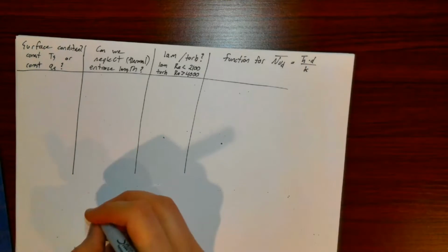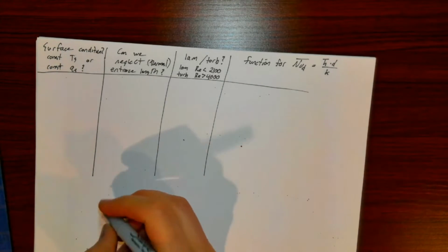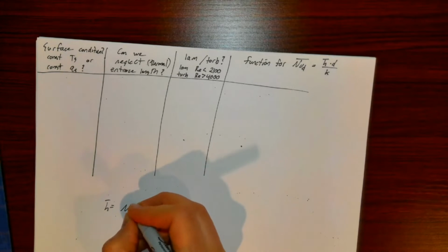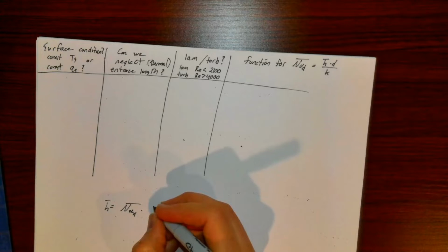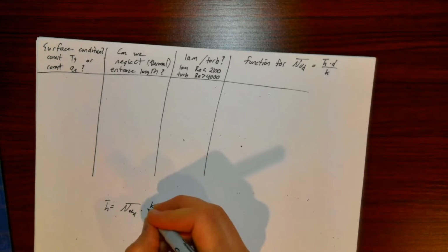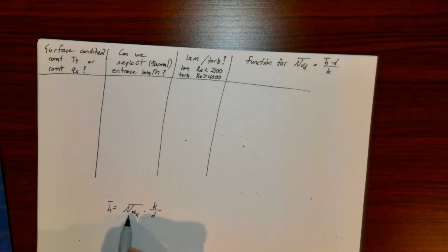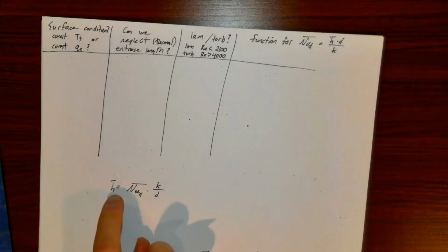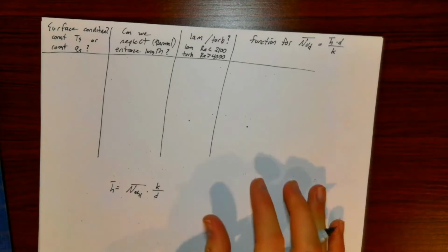so we can turn this around pretty easily. Once we use this function to calculate Nusselt number, then we can say our h is going to be equal to our Nusselt number times k of the fluid over d. So that gives us basically all of the information we need to find our own h. And then we can pat ourselves on the back for having found h, or we can use this h in whatever heat transfer problem we were trying to solve.